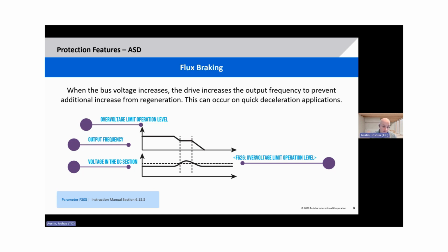We've also used features like this on pump jack applications just to increase the speed of the motor. Even though you're not decelerating, when you increase the speed of the motor to match the actual rotation speed, then you're decreasing the amount of regenerative energy that's being created.